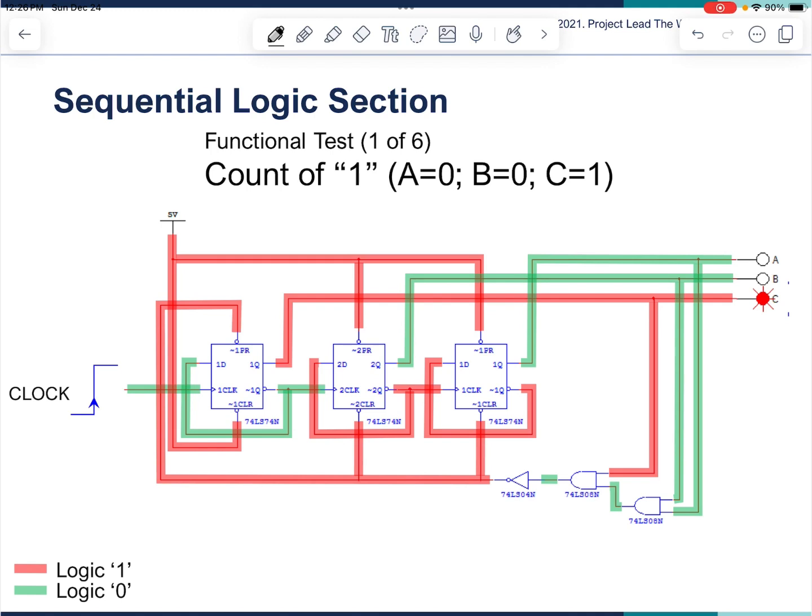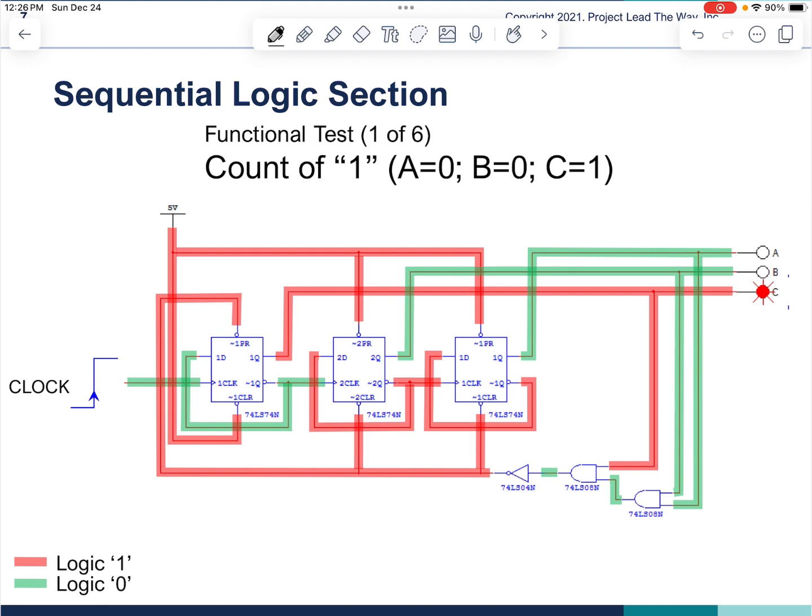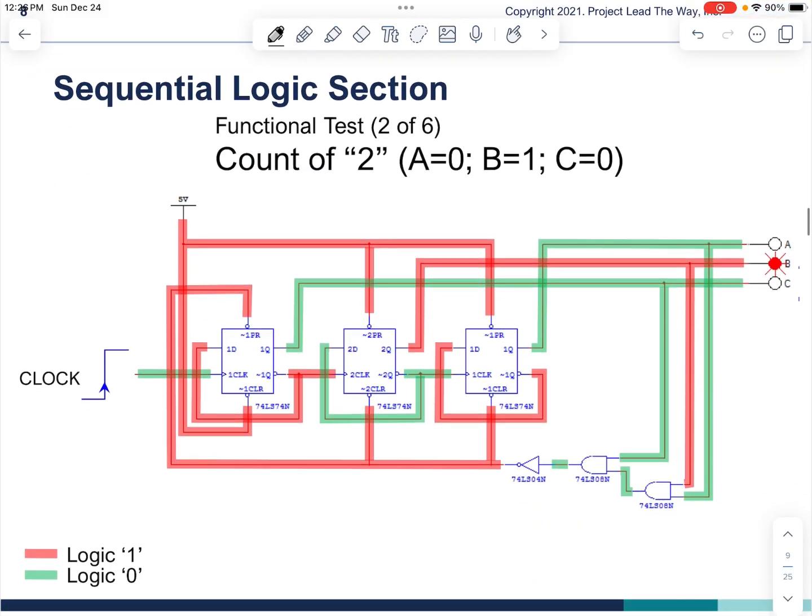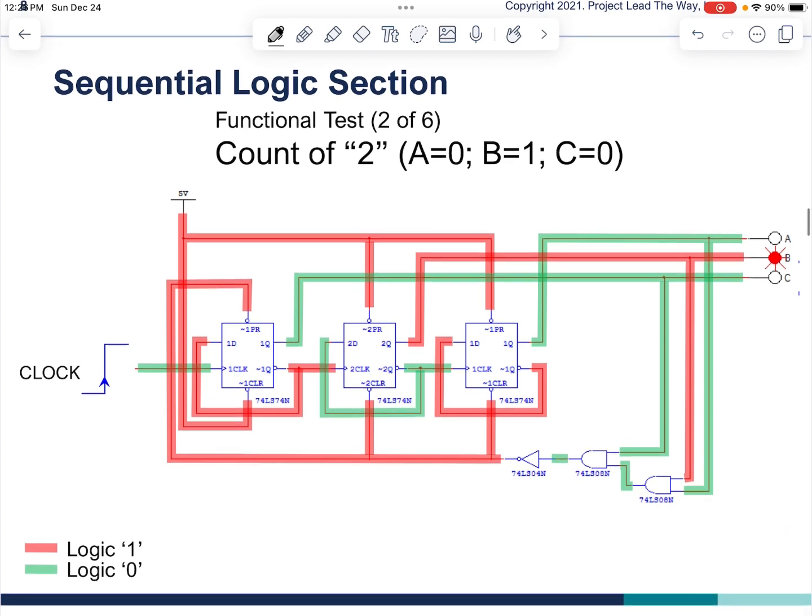Let's look at it step by step. At this point, I suggest you ignore the colors on the slides, because some people get confused. Just listen to my explanation. The first slide is showing the reset circuit. After the reset circuit detects 111, it will right away change the output to 001. In the second slide, you had 001 previously, and we also know Q naught is opposite of Q, so this is 1 opposite 1 and 0.